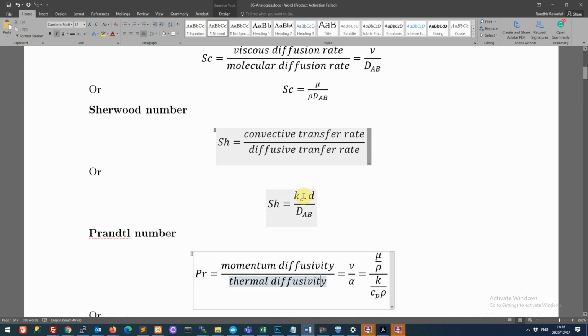So, for example, the mass transfer coefficient. Now, we had talked about a way to estimate it. We said if we know the diffusivity and if we had the film thickness, then we could estimate this value. However, it's almost never the case that you can estimate a film thickness. And the moment you change the geometry of the system, the film thickness will change also. So it's not typically easy to get a number for Kc.